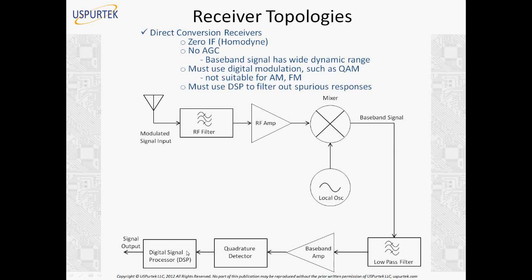By modern, I mean the cellular communication receivers, the LTE receivers, the wireless LAN receivers. All of them have direct conversion receivers, because it's more cost effective and because the processor is readily available in these devices, in the handsets. The older radios didn't have a processor. Your car radio may not have a processor. It is just an analog AM or FM receiver, that's it. But in the case of a handset, you already have a processor inside and you can implement DSP techniques to compensate for gain, selectivity and other benefits that we earlier had with superheterodyne receivers.